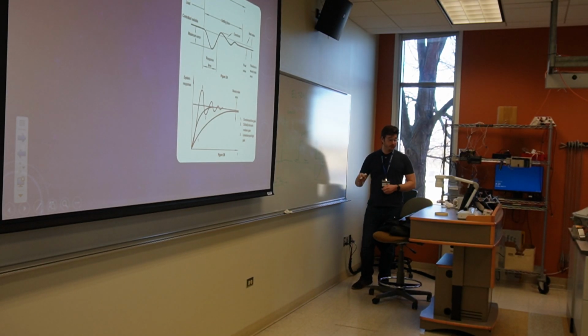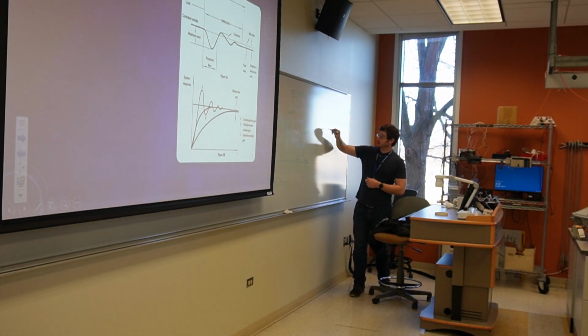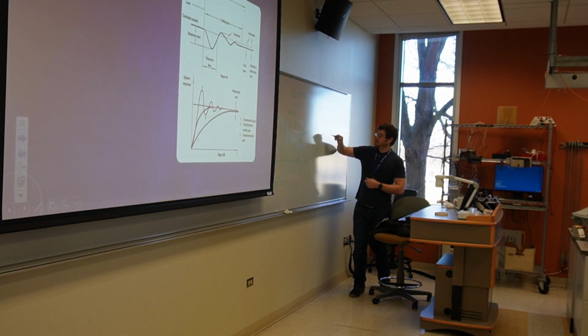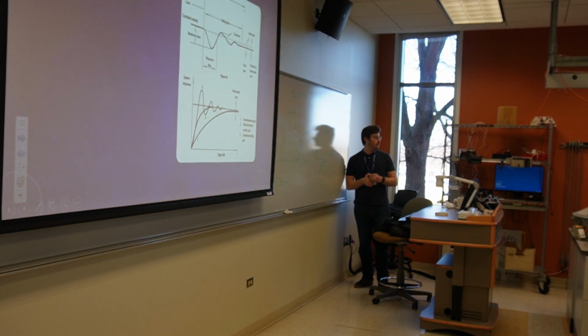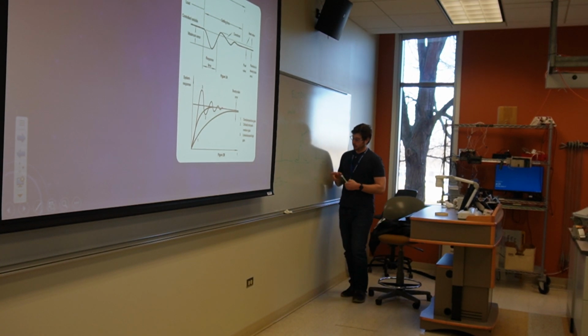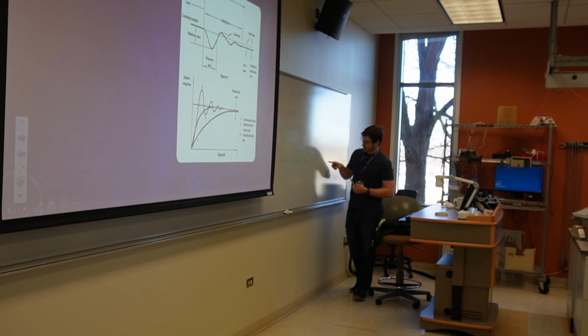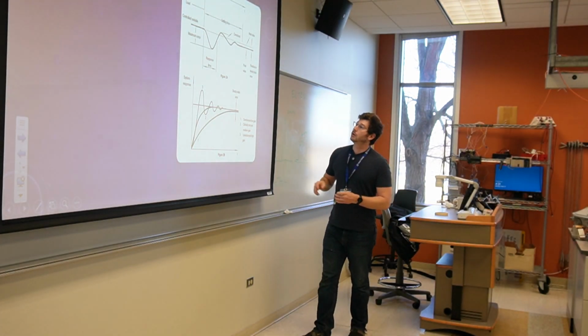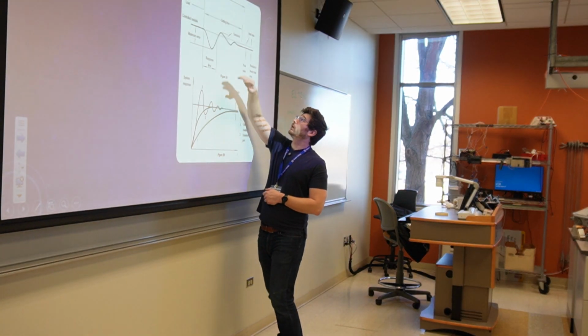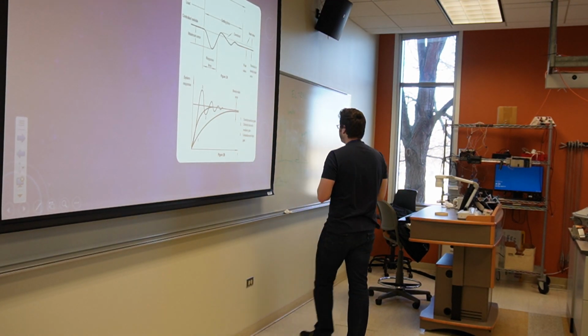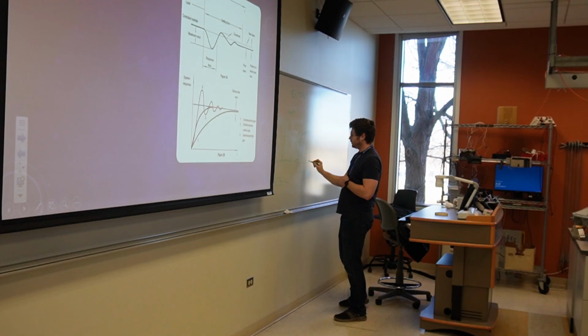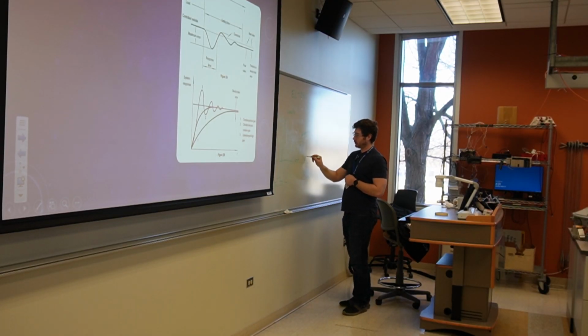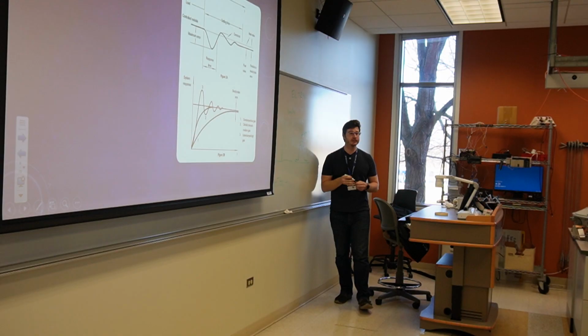It's a really difficult problem, actually, because if your glucose is high at this point in time, you don't actually know what it's going to look like down here when the effect actually kicks in as a result of that medication. So it's a difficult control problem if whatever we're affecting here doesn't come into effect until 15 minutes later. That kind of response time can be very difficult to manage. So that's response time. Also settling time. If we give this impulse, how long does it take to come back down to some percentage of what it was before? It can be called settling time.